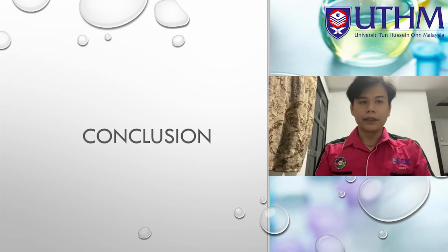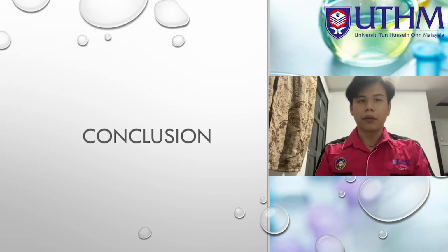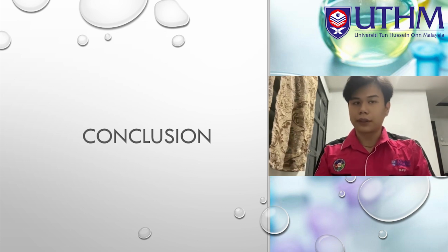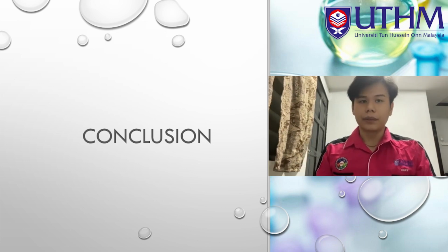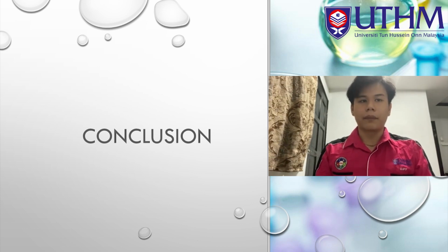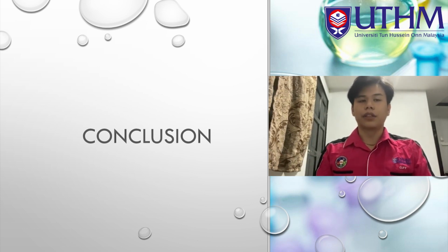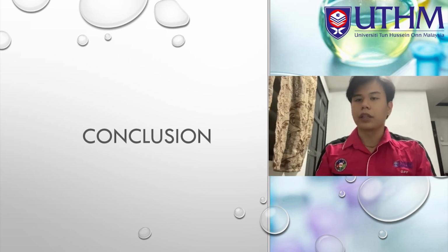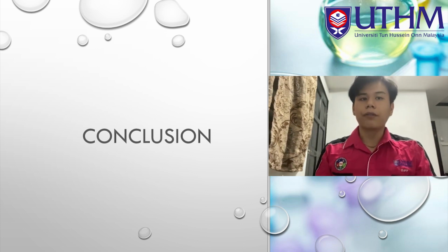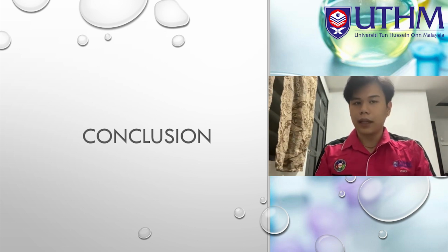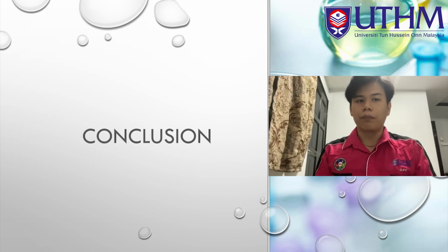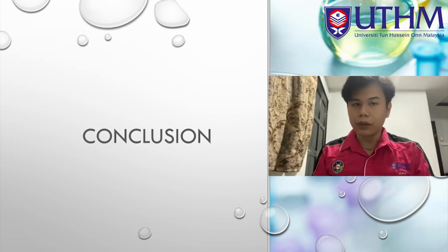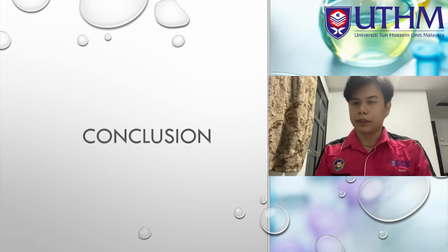For multiple planes, it was found that the experimental condition and theoretical condition were the same under the consideration of static and dynamic conditions. Experiment A of dynamic balancing was in imbalance condition because the resultant turning moment along the axis of the plane was not equal to 0. Meanwhile, experiments B, C, and D were all in balance condition for both static and dynamic balancing. Overall, the experiment was a complete success.